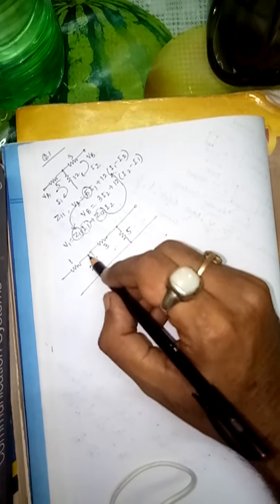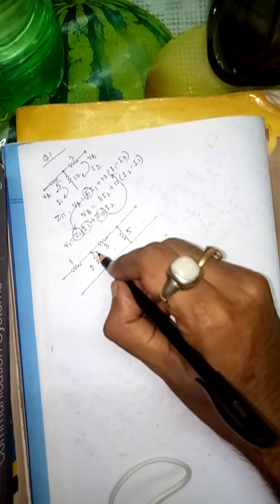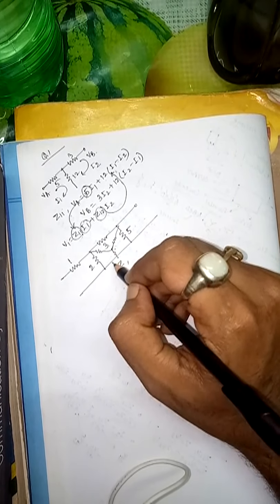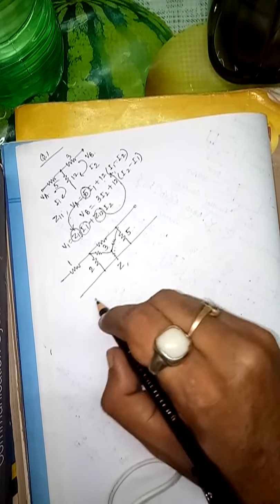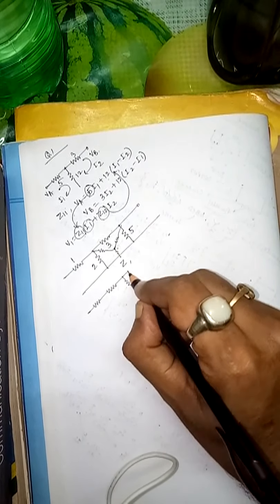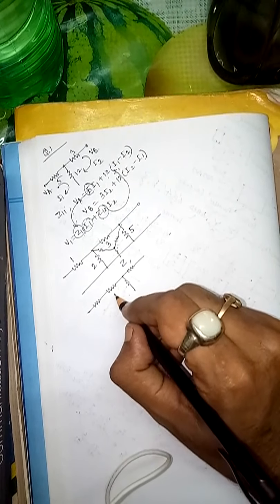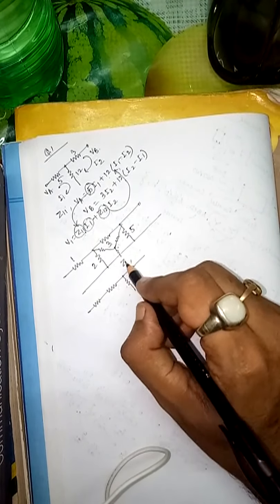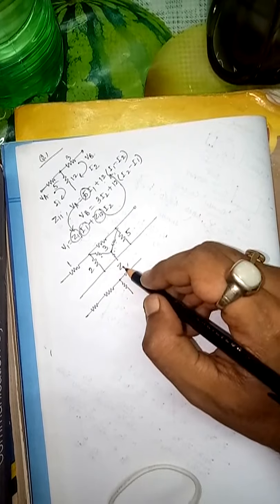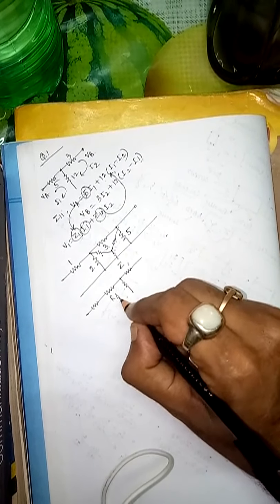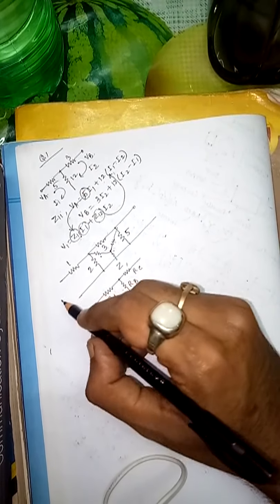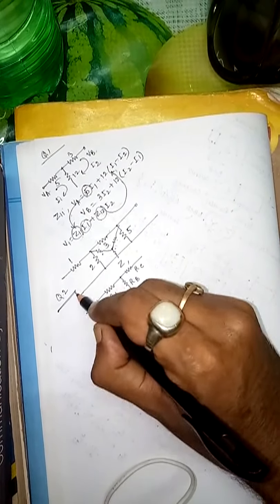First of all, you can see this is a pi shaped circuit, so you can convert it into the delta form, like star to delta conversion. You can change it in this way. So the entire circuit will look like this: first one, then the second one, then the third one, and then the fourth one. What is the equivalent resistance? That is the star to delta conversion you have to use to find this equivalent resistance, as I have discussed in my earlier lecture. Then you have to replace this value RA, RB and RC. So follow the same way to solve this particular problem, that is question number 2.